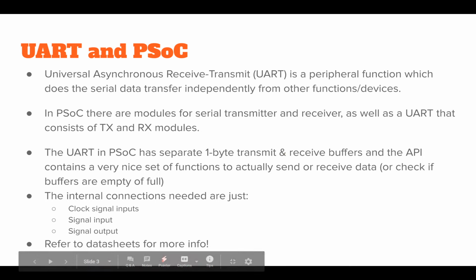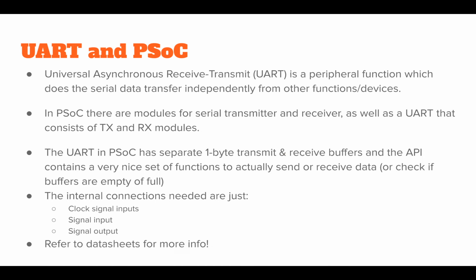Okay, so UART, universal asynchronous receive and transmit. That's where the acronym actually comes from. And actually it's a peripheral function which does serial data transfer independently from any other functions or devices. The PSoC actually has modules for serial transmitter receiver as well as UART, and you already have used this UART line.